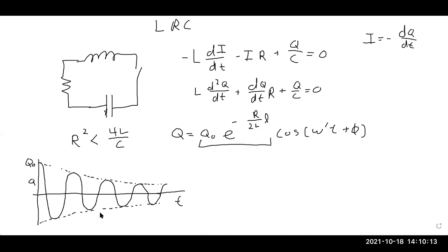Whether it gives off pulses of heat or steady heat depends on the thermal properties of the resistor, because it's very possible that the time scale for it to release its heat into its surroundings is substantially longer than the period of oscillation of this circuit. So it would get warmer in bursts, but as long as it's warm, it's still going to be radiating that heat off into its environment.